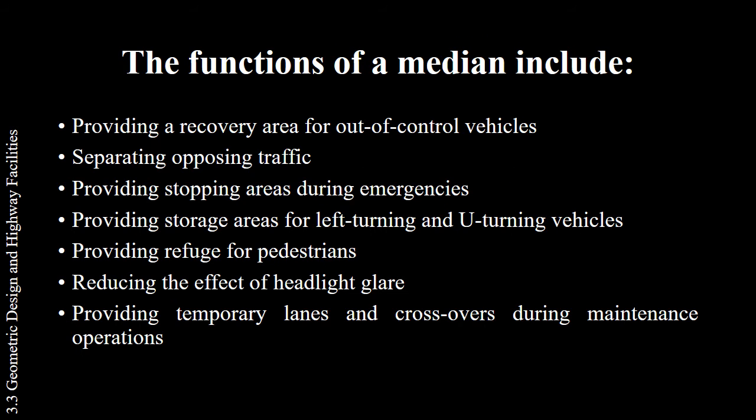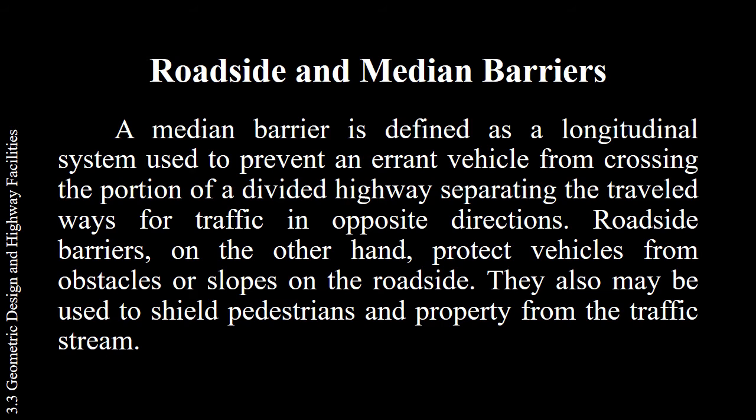The functions of a median include providing a recovery area for out-of-control vehicles, separating opposing traffic, providing stopping areas during emergencies, providing storage areas for left-turning and U-turning vehicles, providing refuge for pedestrians, reducing the effect of headlight glare, providing temporary lanes and crossovers during maintenance operations, or slopes on the roadside. They also have been used to shield pedestrians and property from the traffic.